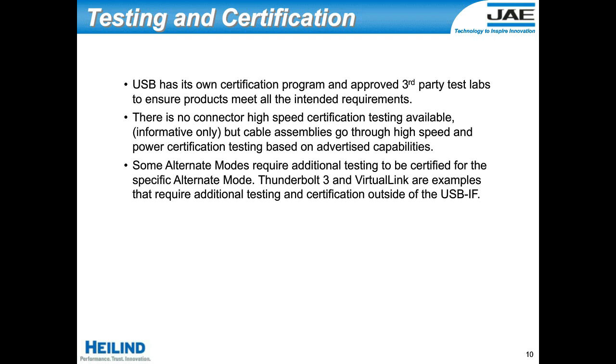Both connectors and cables do go through basic mechanical testing, such as contact resistance, temperature cycling, mating durability, and retention force. The cable side also has some additional cable flexing and wrenching torque force testing as well, which is somewhat new. USB Type-C also now uses new calculation methods to validate signal integrity performance rather than your traditional insertion loss, return loss, or crosstalk plots.